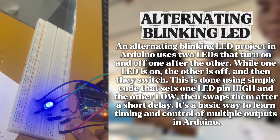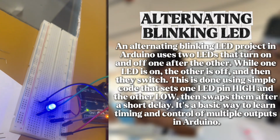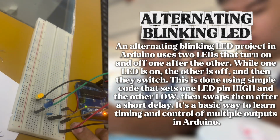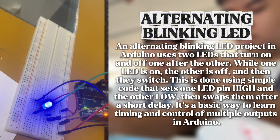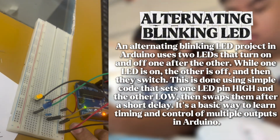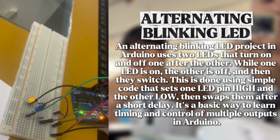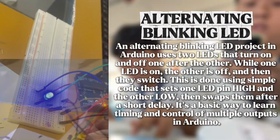An alternating blinking LED project in Arduino uses two LEDs to turn on and off one after the other. While one LED is on, the other is off, and then they switch. This is done using simple code that sets one LED pin high and the other low, then swaps them after a short delay. It's a basic way to learn timing and control of multiple outputs in Arduino.